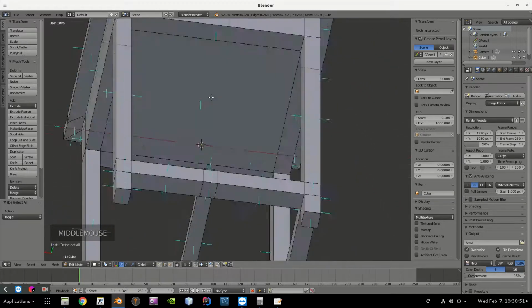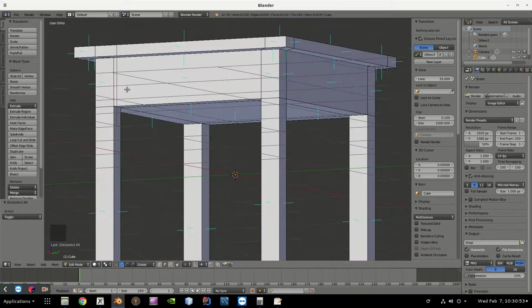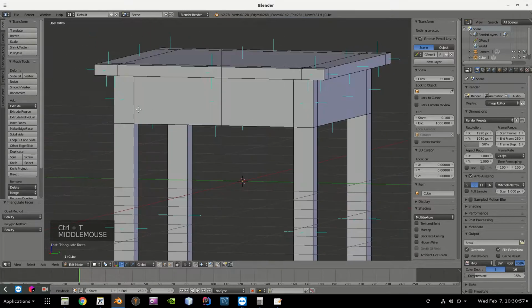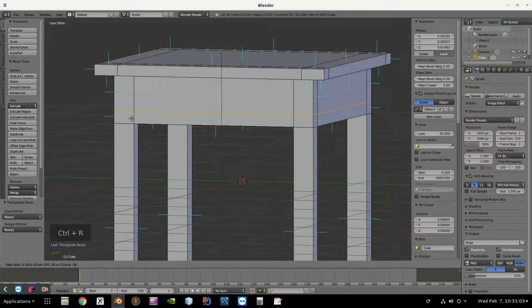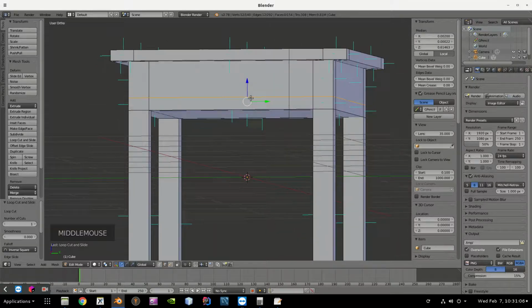We can use loop cuts. All right. So we can introduce a loop cut right here, and the way it is, this drawer, we don't have any gap over here. It's right at the top surface, right? So I was just looking for that. Otherwise, I would introduce another loop cut over here. We don't need to do that.